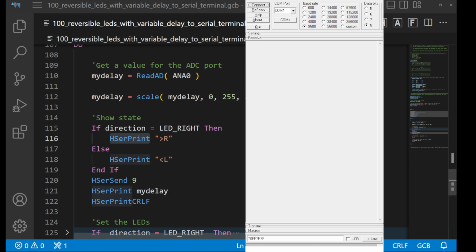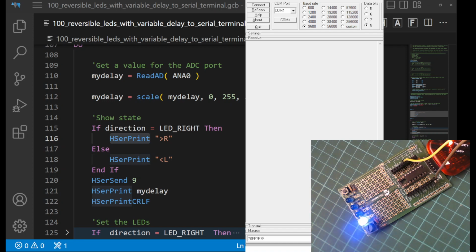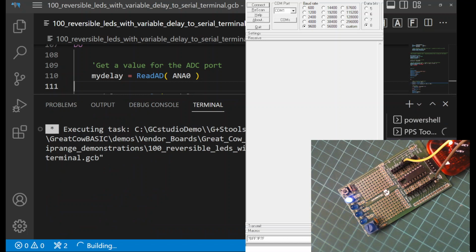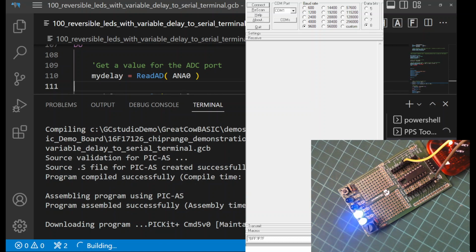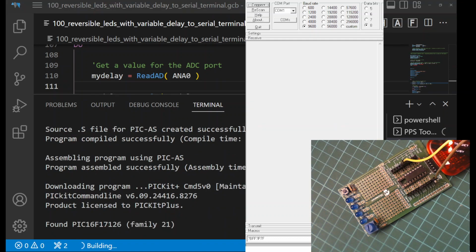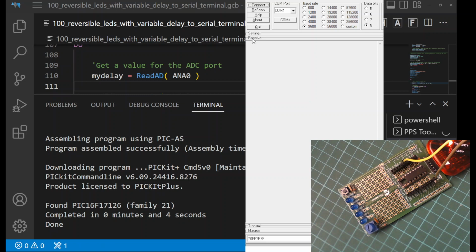Let me bring in another item. Let me bring in the lab, and we can see it's where we left it yesterday. Let me program it by pushing the hex and flash, and it will program it. The terminal at the moment is not connected. It's purely opened up the session for you. Now, if I look at the application, I need to select the communications port that I'm using. Well, I know that it's on COM10.